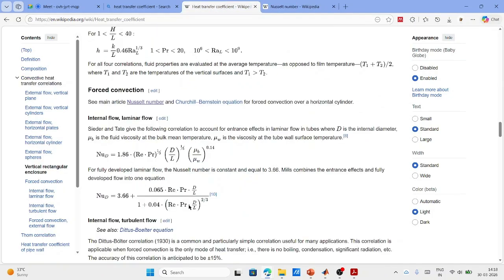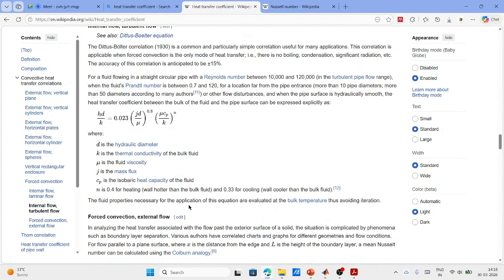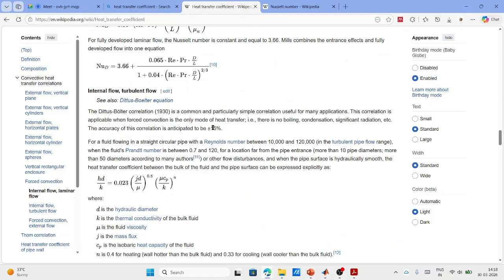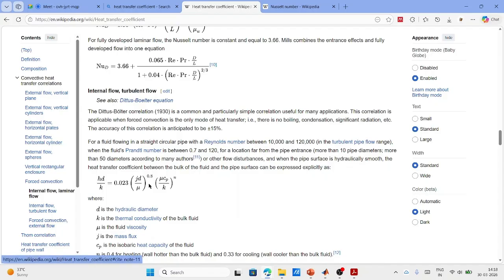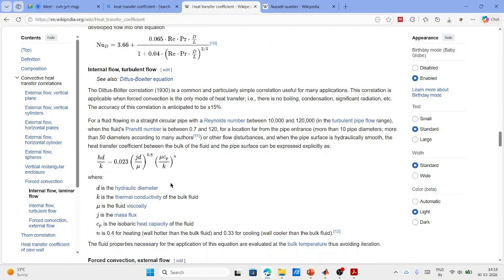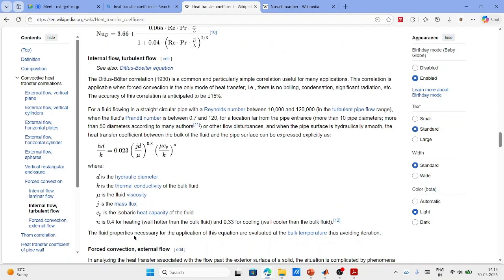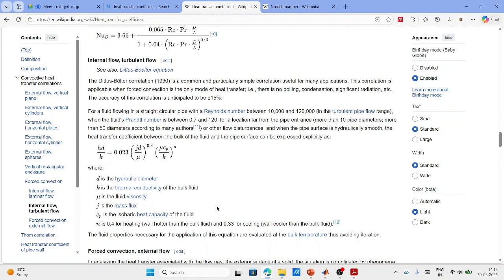So we have learned that when you are in a laminar region, Nusselt number is given based on the Dittus-Boelter equation, where Nusselt number is related to the Reynolds number to the power 0.8 and Prandtl number to the power n, where n could be 0.4 or 0.3 for heating and cooling application, right?